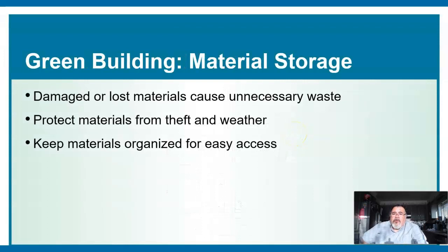Green building, material storage. Damaged or lost material causes waste, right? So you've got to put the material away. It's got to be in a dry place. If you leave it, it can't be touching the ground. It has to be up on pallets. If it doesn't, it'll draw moisture, and especially if it's cement or concrete pre-mix, it'll go to waste. So protect your materials from theft and the weather, and keep materials organized so you can get to them easily. Concrete can get messy.